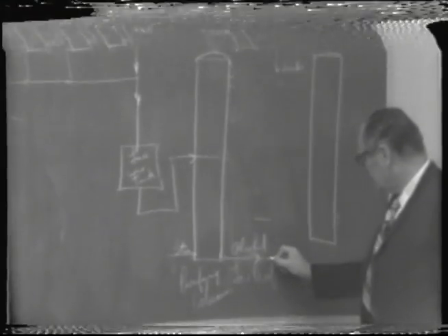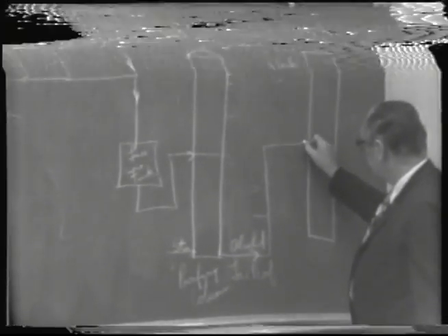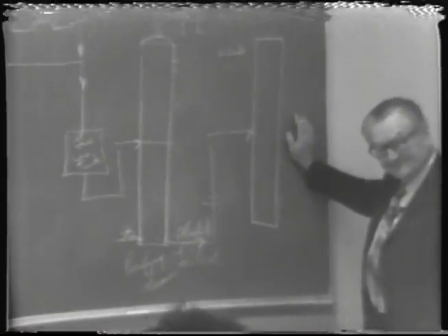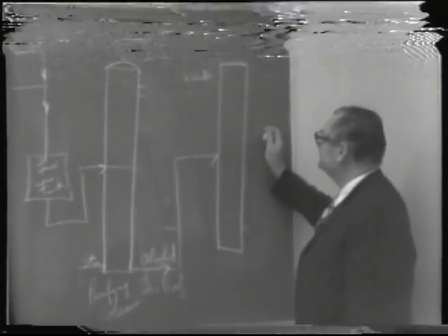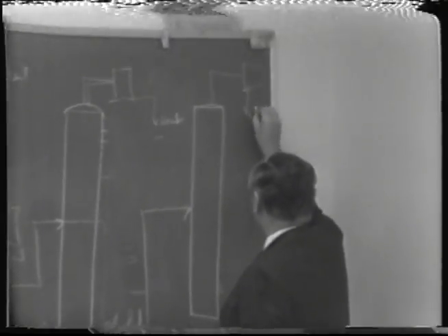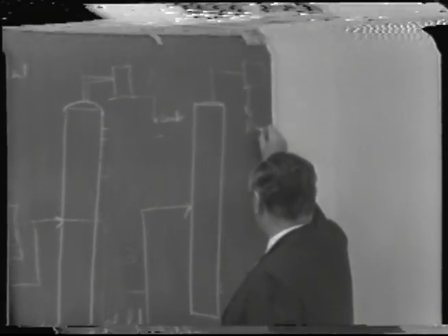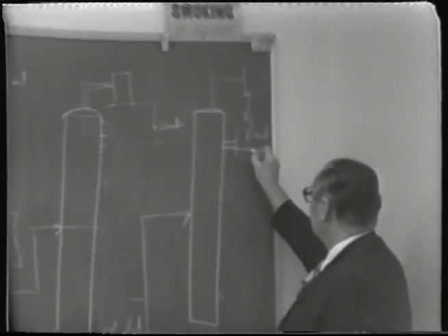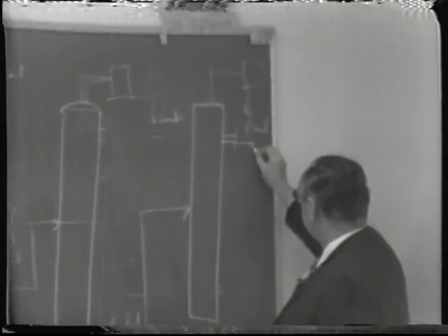Now this low-proof alcohol would be fed into the middle part of this final column, which would be a concentrating column, the concentrating section. And of course it'd have its condensers up here, and you might have a small heads cut taken off here, and you might take the product off as a side stream a few trays down from the top, the spirit.